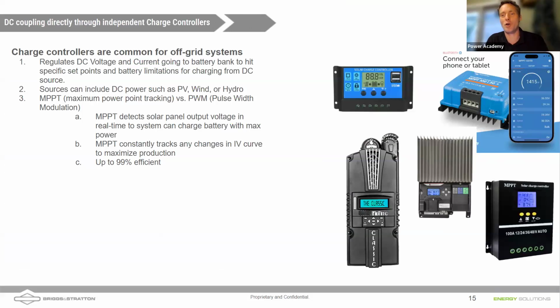That's a DC charge controller that many of us have probably installed. There's a little PWM controller up there on the top as well. Those units go for about $10. And then there's the Victron system. Those Victron smart charge controllers are commonly used, especially in mobile applications. So a number of different examples. Typically, charge controllers are current limited, and they have a range of voltages that are acceptable. I think with the Midnight Classic 100s that are out now, you can do 100 volts of incoming solar. It might be up to 150 with those.